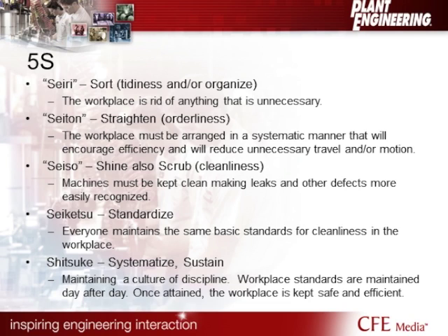Seiso, or shine, also scrub, I've seen in some facilities here in the U.S., and now we're getting into that cleanliness piece. We're making sure that if we take the machine to that clean level, we can identify defects very quickly. Very core to doing good maintenance. If you have oil leaking everywhere and the equipment's covered with dust and dirt sticking to that oil, then it's very hard to see the source of that leak. It's very hard to identify new issues or new defects getting introduced to the system. So this is all about cleaning away the debris so that we can really understand how that asset performs.